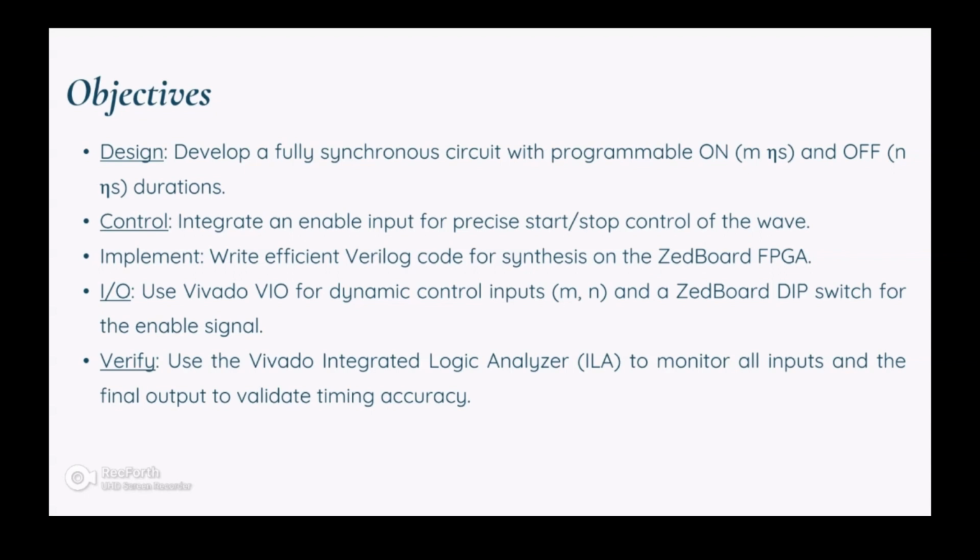Platform implementation. The logic is captured in Verilog HDL for efficient utilization of the FPGA's resources. We use Vivado VIO to supply the dynamic control signals and a dip switch for the external enable input.